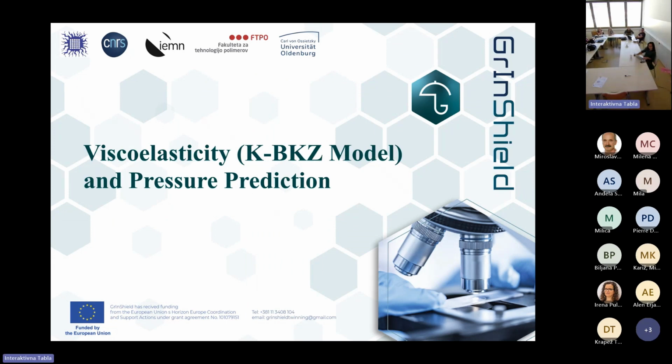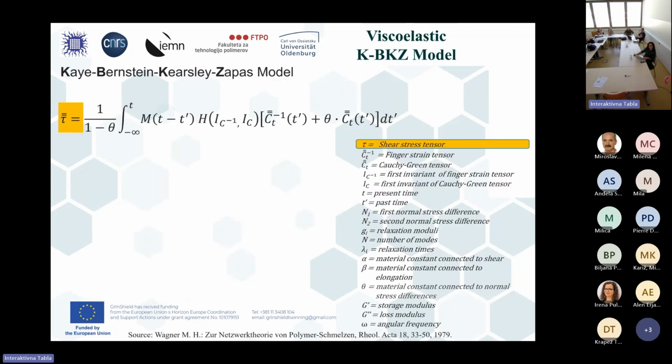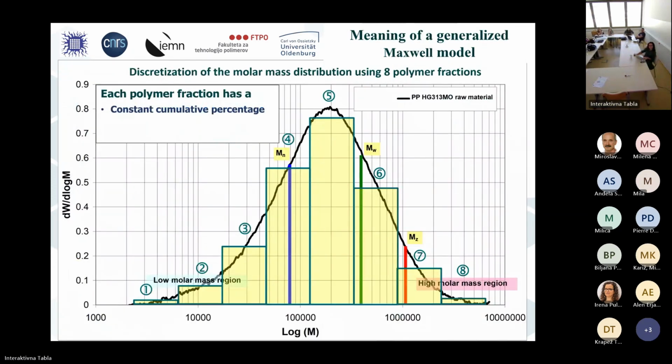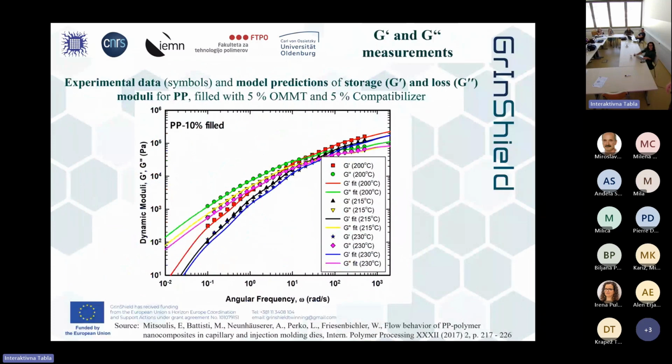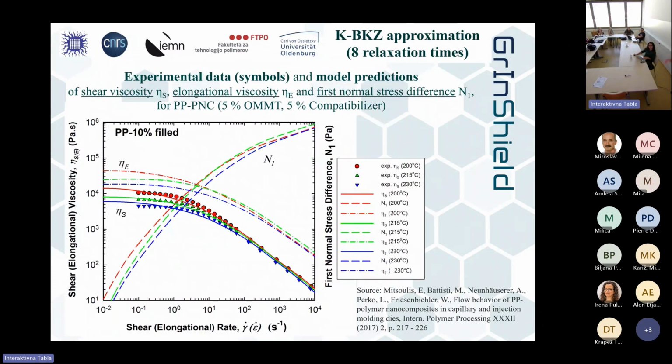So, I will stop now here. That's a very complicated topic, viscoelastic modeling. I show you only: you measure with the cone plate rheometer the dynamic moduli, G prime, G double prime. Then you set up a so-called spring damper model, Maxwell model, but with 8 elements. And out of these measurements, you can find out the elongational viscosity, the first normal stress difference.